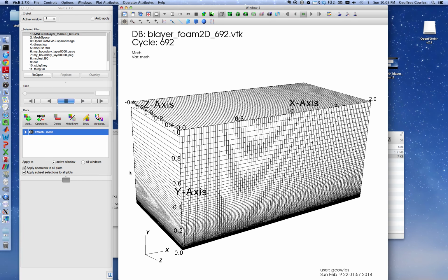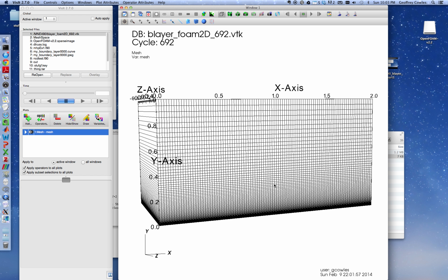Now I have it set up so the flow is going in this left face, out this right face. It's flowing over the plate, which is at the bottom. Now I've set up the boundary conditions so the flow's coming in. The dimension of the domain is too long, but as I mentioned before, the plate is only of length 1. The real plate starts here at 1. Prior to that is inviscid flow. It's a slip condition at the wall.